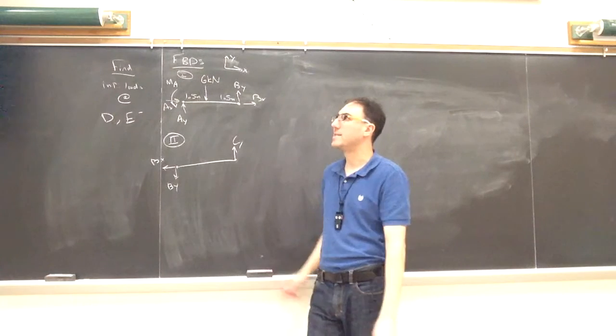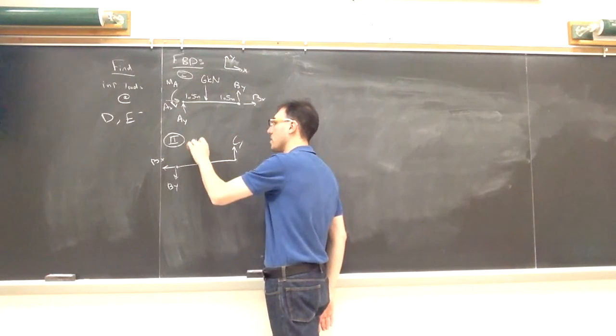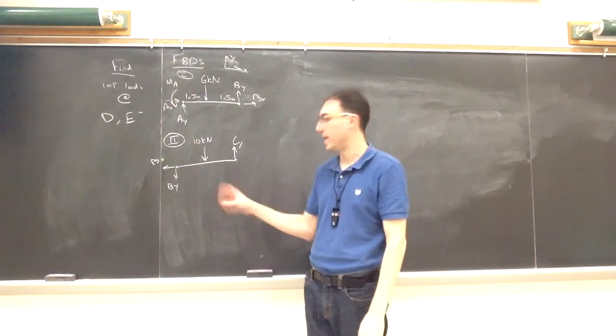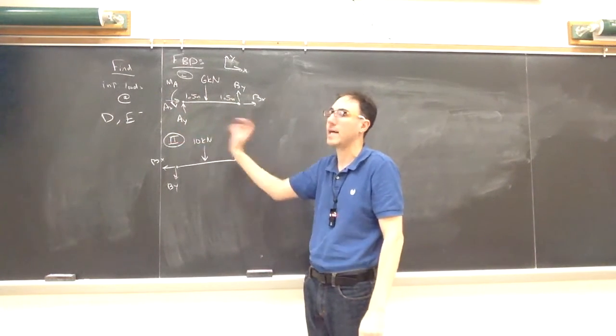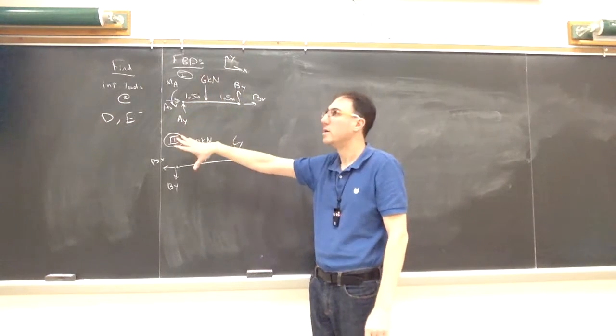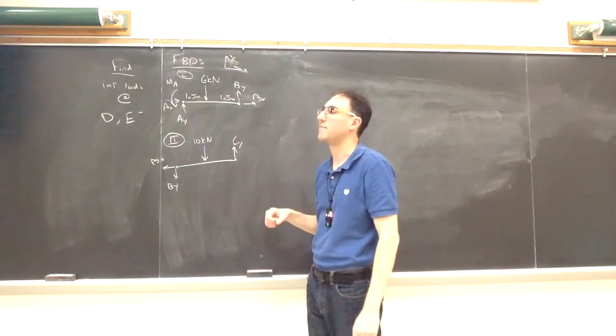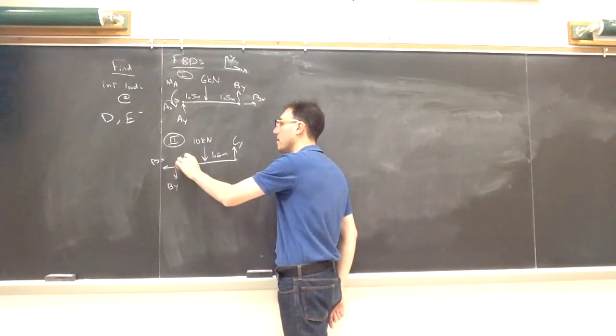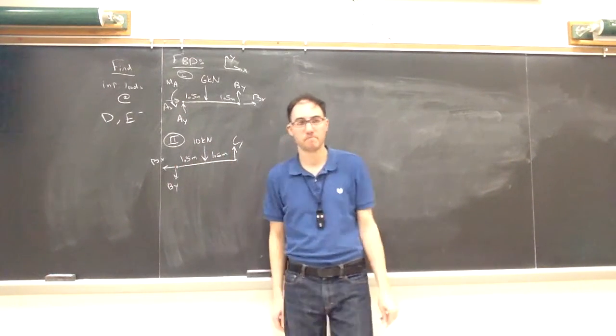And the beam from B to C has this 10 kilonewton force, but B to C doesn't know that there's a distributed load happening because that's happening on member number 1. So in member number 2, I just have to compensate for that point load here that's also acting in the center of this beam of 1.5 meters.